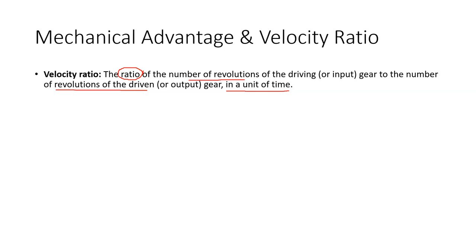It can be based on the number of teeth of the gear, again assuming the gears have the same diametral pitch. It can be based on the overall diameter of the gear, which is tied right to the radius. And it could be based on knowing the actual velocity, usually the rotational velocity or rotational speed of the gear, which is just another way of saying the RPMs of the gear.